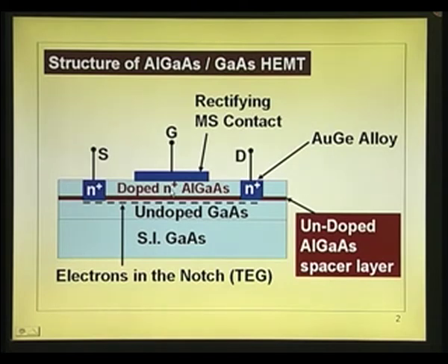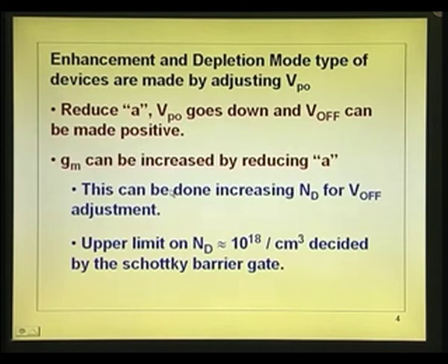So, the upper limit comes up by the doping concentration there. So, you are stuck with that, and you are stuck with a certain layer thickness. Okay. So, Gm upper limit is there because of that. But of course, you can always play with the velocity overshoot effect and very short channel lengths and very high fields to get high velocities, better transconductance.